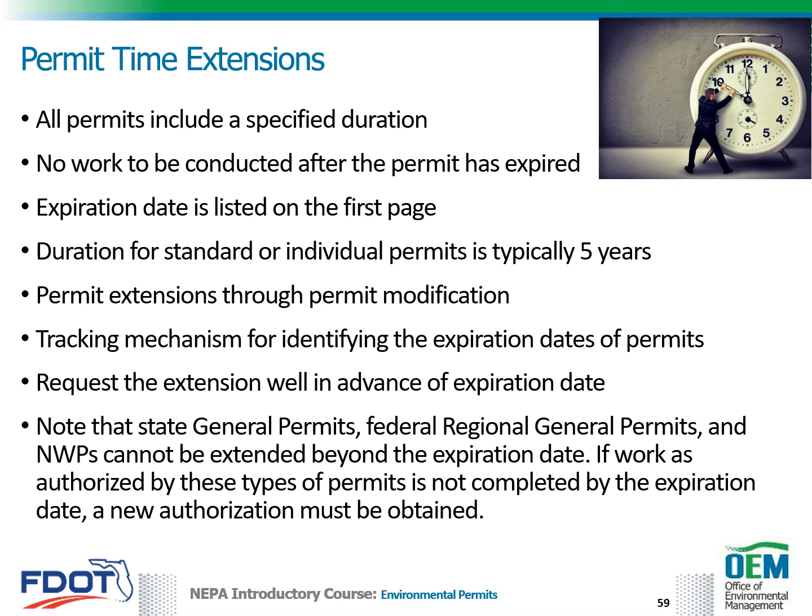All federal and nationwide permits are issued on a 5-year basis, and therefore all expire on the same date. Current nationwide permits will expire on March 18, 2022. When a nationwide permit is issued, the expiration date is clearly identified. If construction on a project authorized by a nationwide permit has begun prior to the expiration date of the permit, FDOT has an additional year to complete the project.